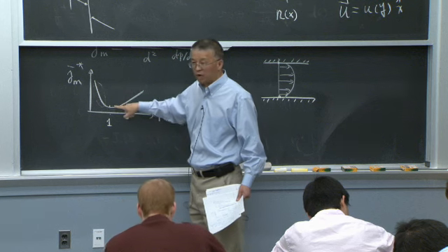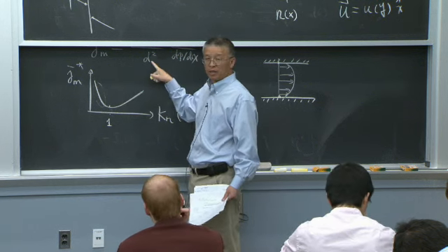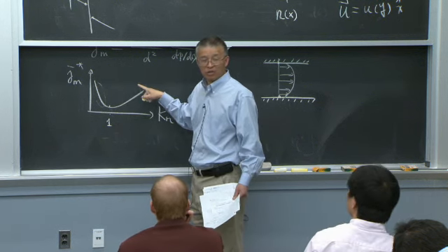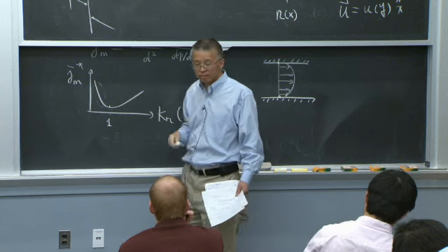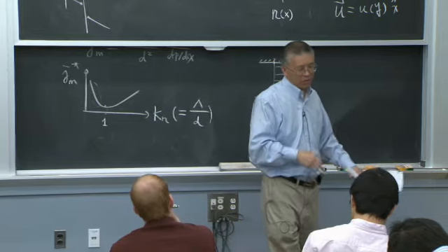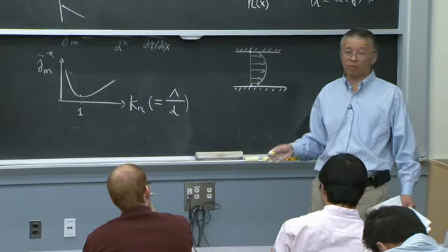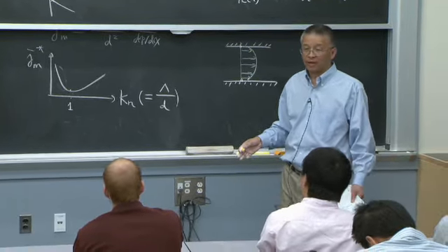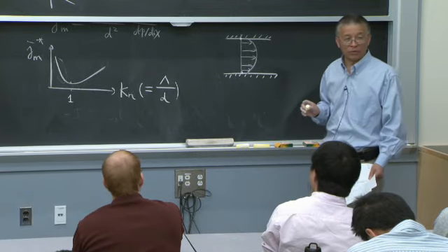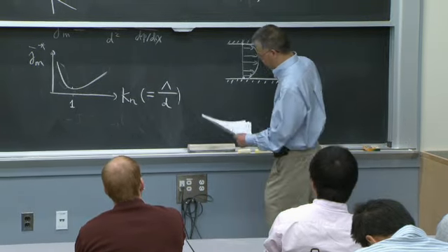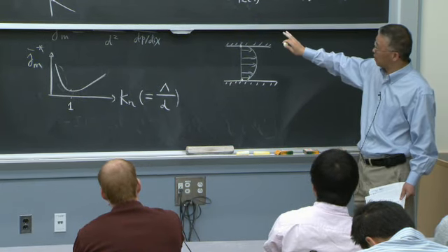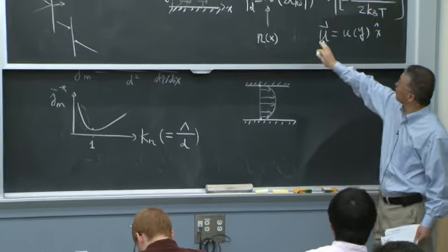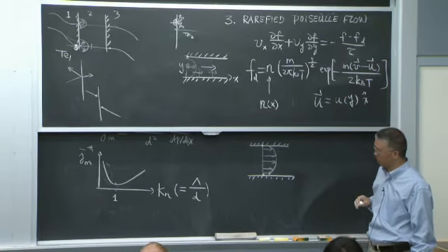With second-order velocity slip, you will over-predict the velocity in this range. So even in those days, there were people still trying to write the boundary condition. And I'll tell you a story about how I derived a new boundary condition next lecture. But this is the Knudsen flow and the rarefied Poiseuille flow, Knudsen minimum.